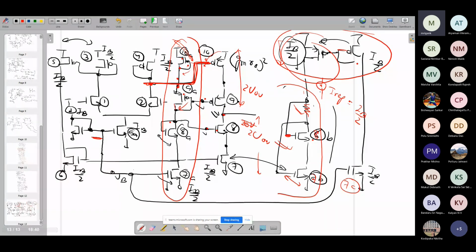The purpose of using these two direct connected transistors, M10A and M8A, is to get appropriate VGS drops. So M7A, carrying the same current as M7, sends that same current into M8, and therefore this is direct connected. It will develop the VGS required for M8. That VG can be applied to this M8, and it will make sure it also has a similar VGS, because M7 is anyway trying to enforce the same current.